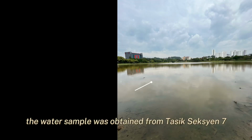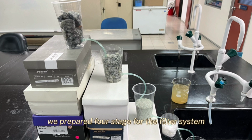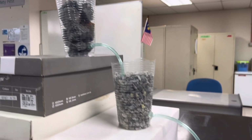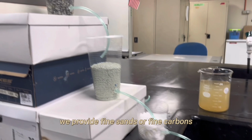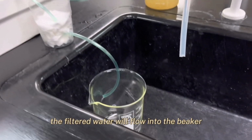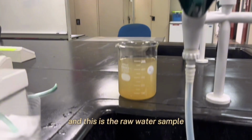The water sample was obtained from Tasik Section 7. This is the water filter system that we use. We prepared 4 stages for the filtered system, where the first one we provide gravel stones, the second one we use small stones, and the third one we use finer materials, where in this case we provide fine sands or fine carbons, and the last one is cotton pads. The filtered water will flow into the beaker, and this is the raw water sample.